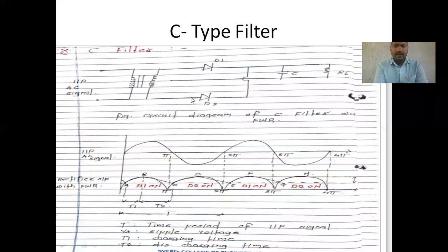So it indicates that the anode of D2 has the positive voltage, so diode D2 conducts, so that the same positive voltage appears across your capacitor, right? So either in your positive cycle or negative cycle, there will be positive voltage coming across your load. This will be the thing with respect to up to this point.